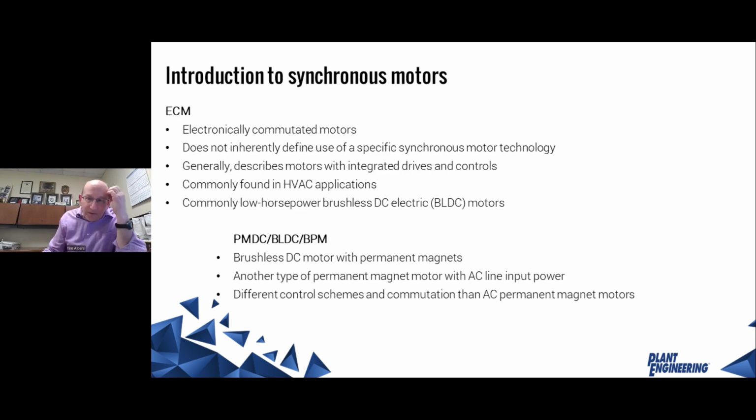One thing that John talked about briefly at the beginning is this point of ECM and PM. There are a lot of terms for synchronous motors. An ECM motor is not anything special. An ECM motor is just a permanent magnet motor or a synchronous reluctance motor of some type that is then just integrated with a drive.